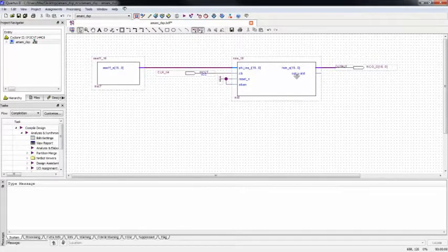And again, we're going to leave this particular output valid flag open. So now we have the schematic captured, we're going to hit save. Okay. We want to run the pin planner first. But before we do that, we're going to want to compile the project.